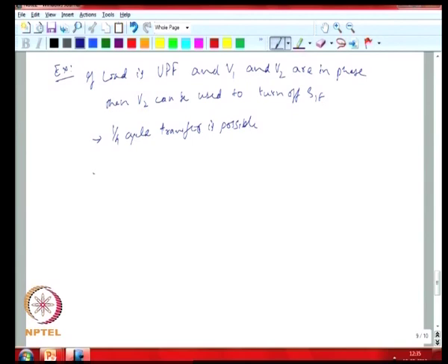And a challenge in many of these transfer switches is to differentiate when to transfer and when not to transfer, because you can have many false trips. For example, you might have some small phase jump or some smaller amplitude changes or some harmonics which might be acceptable. So, how to make a decision when to transfer and when not to transfer, that is actually a challenge in a transfer in such a configuration.